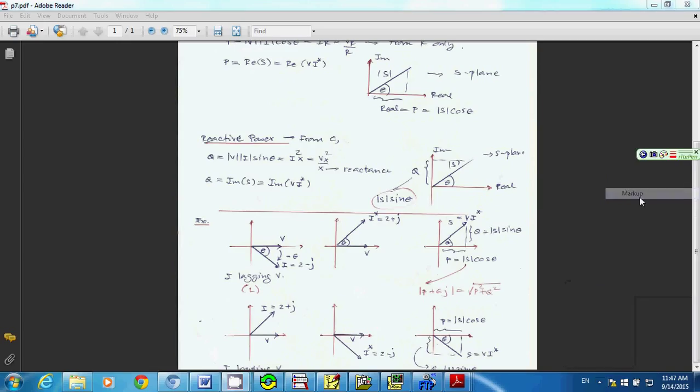What about here? Well, in the case of an inductor, I is lagging V, right? The phase of I follows the phase of the voltage. So that's why I have I here. It follows the phase of the voltage, because you take a look in the direction of counterclockwise. So if you have I equal to 2 minus J, this is just to get a better picture. So my I complex conjugate, because you are looking for V multiplied by I complex conjugate, right? My I complex conjugate becomes 2 plus J. So that's why I have I complex conjugate up there.